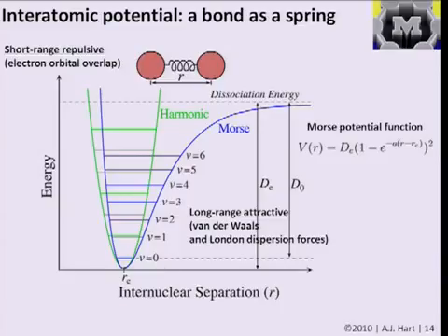But what we're going to use it for today is to get a simple representation for the stiffness of our bond. Because what happens as you play with this spring, say you're able to take your material, go in to a really small space and cut out just one bond, and you have the bond sitting at its equilibrium separation. If you push the bond together, so you push the atoms closer to each other, you eventually feel a repulsive force. And this can be thought of as the electrons around each atom electrostatically repelling each other, pushing each other apart. And then if you pull on it, go in the other direction, you'll feel an attractive force, and it'll be like stretching the spring and feeling like the atoms want to go back toward each other.